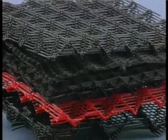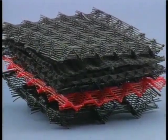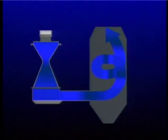Mesh pads are made from interlaced fibers that serve as the collection targets. A cyclone is typically used for the small droplets generated in a Venturi scrubber. The gas stream exiting the Venturi enters the bottom of a vertical cylinder tangentially. The droplets are removed by centrifugal force as the gas stream spirals upward to the outlet.